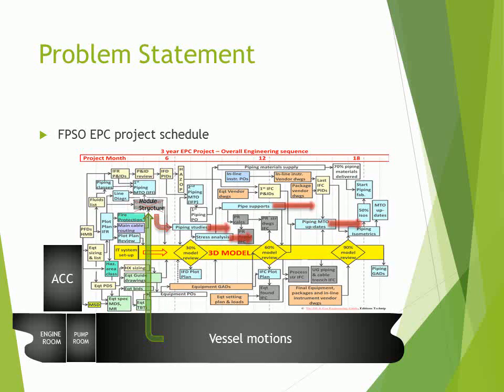On an FPSO, the hull and marine inputs were an important input to the design of the topsides. Vessel motions introduce stress to the module structures. Those stresses must be considered in the piping stress analysis. Pipe sizing and routing can proceed without much impact since the equipment layout can be fixed early on, and the starting and ending points of the pipe will not change much.